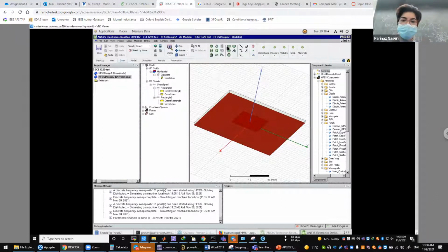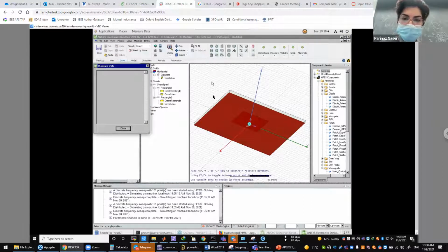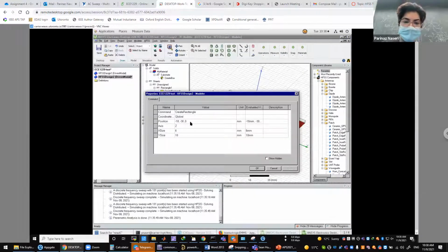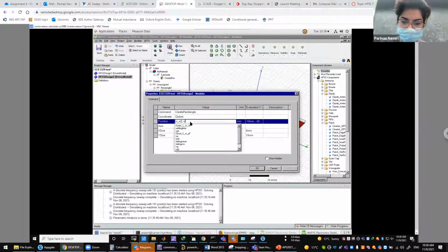Okay, so now let's make this slot, basically. Again, I'm gonna make a rectangle and then work with it. So let's go exactly with what we said here. So we're going to go with minus Sx over 2, minus Sy over 2 plus some offset Y, I'll call this slot offset.